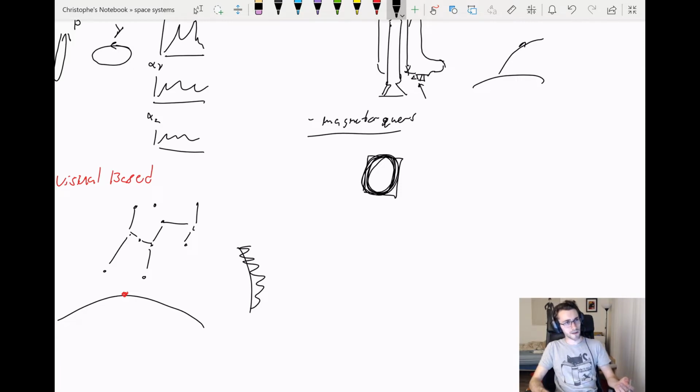How magnet torquers work is they just induce a magnetic field. And you might be thinking, well, how does that actually change your attitude? So we've got one lead here and another lead out here. We apply positive voltage, and there's some current running through it, which means that according to the right-hand rule, the magnetic field would be going through the loop, and looking from the side here, if that was our positive voltage, this was our current, the magnetic field lines would go something like that.